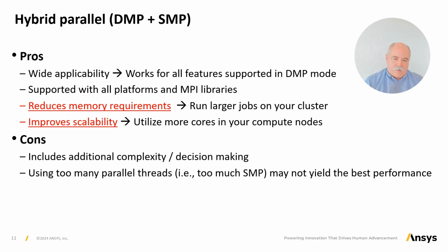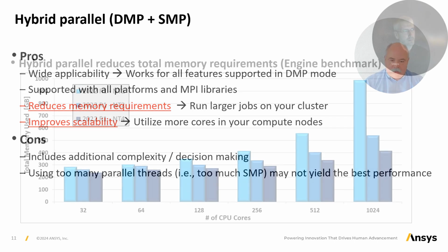However, when you have a rather small model and a lot of hardware to run on, it's an option to run with, let's say, 2 or 4 threads in parallel to achieve a better performance than running single-threaded. Depends a little bit on how large the model is and how much work is to be done for each compute core or each thread on your hardware.